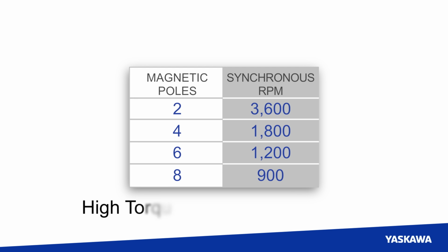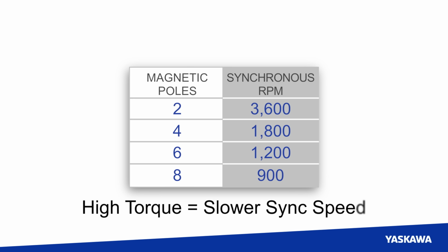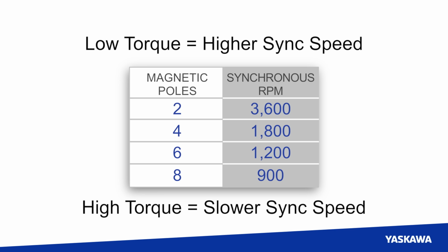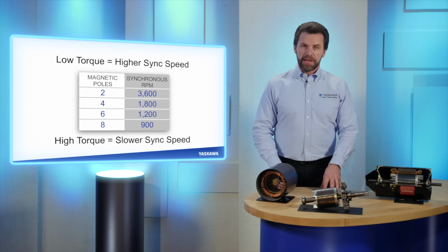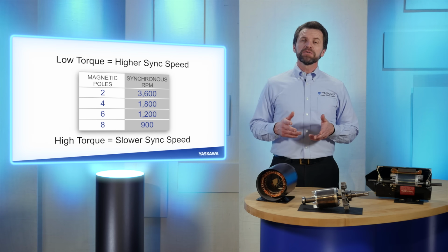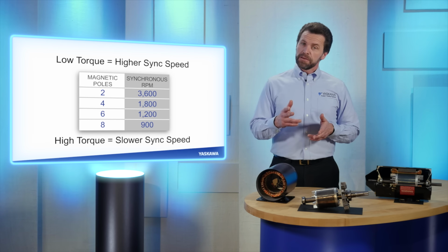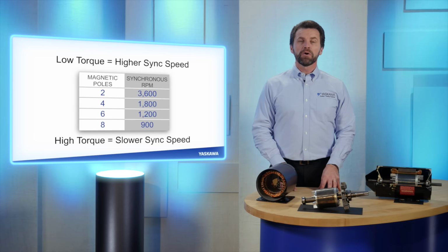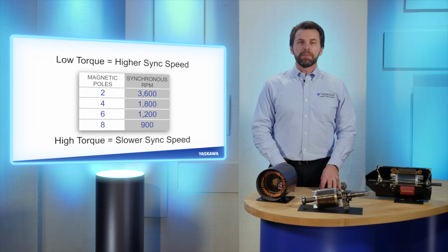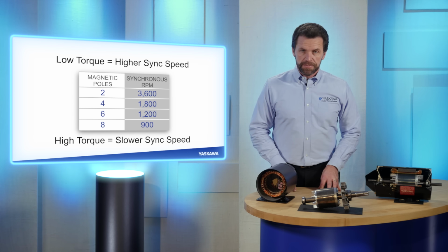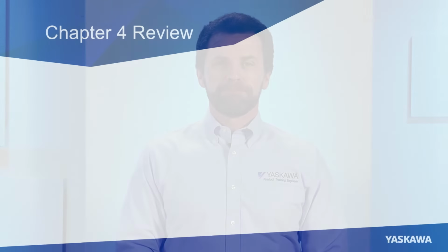So, high-torque induction motors have slower sync speeds, and lower-torque motors of the same size have less torque and higher synchronous speeds. One thing to note, as pole count increases, so does the cost of manufacturing. So most induction motors are 2- or 4-pole configurations. If more torque is needed, most people will opt for a physically larger motor instead of using a 6- or 8-pole machine. Well, it's time for yet another quiz question.